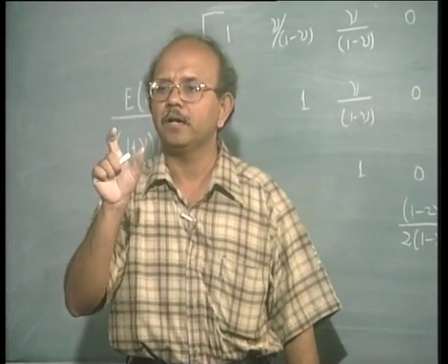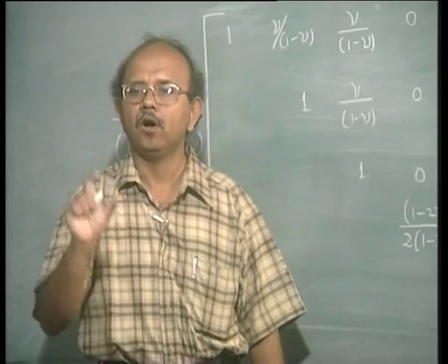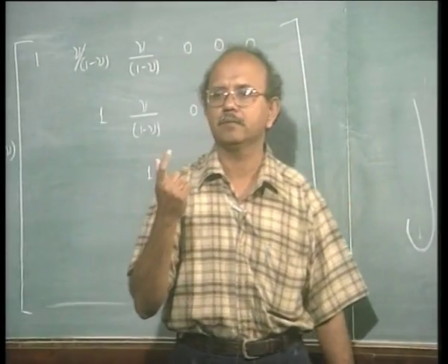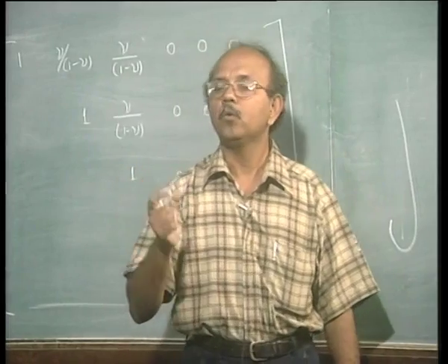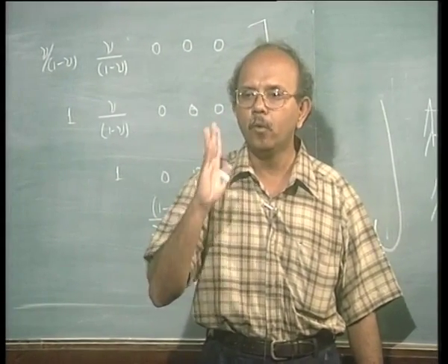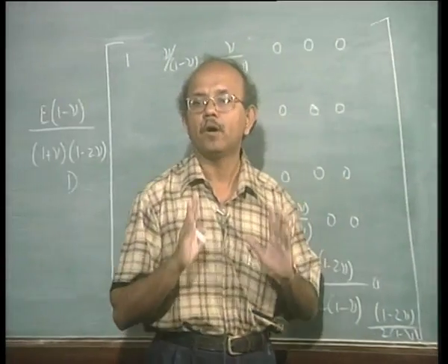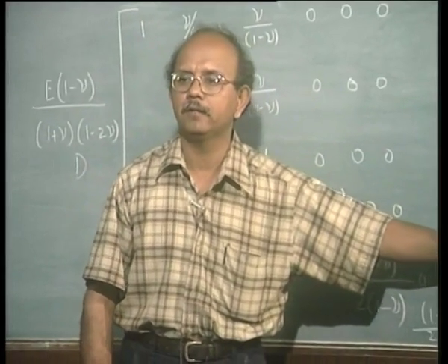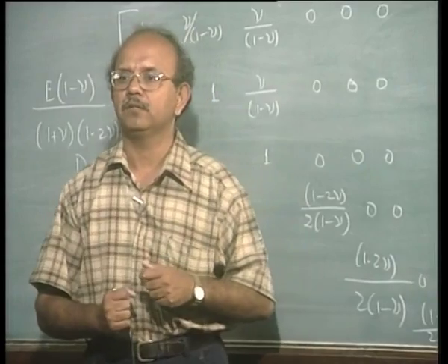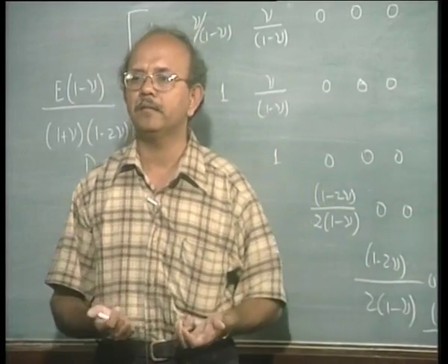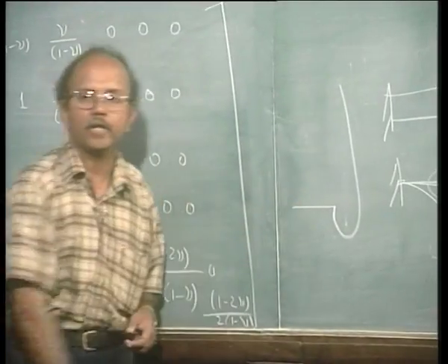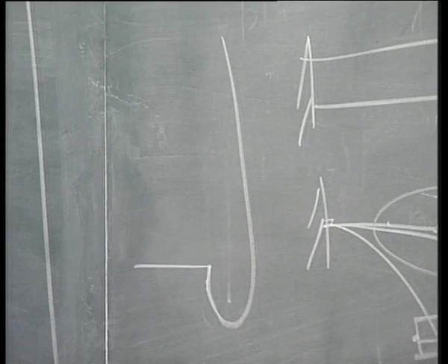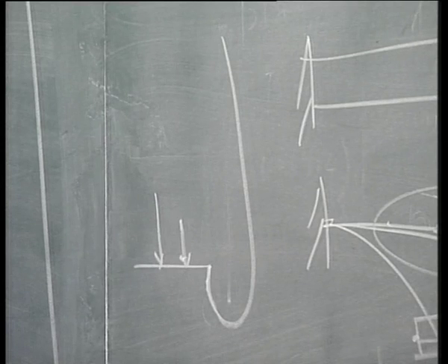There has been a lot of work done, with some assumptions and some simplifications, as far as that degree of freedom is concerned. We will not worry about that right now, but my whole aim at this point of time is to tell you what a shell is and where it can be used. Obviously, in this case you can't use a plate, because there can be in-plane stretching, because this sheet is not only going to be bent but also stretched, because it is welded to the undercarriage, and hence the behavior becomes complex, and hence we have to use a shell element. But as I told you before, most of the commercial packages have a plate shell element, and hence we do not have much of a problem.